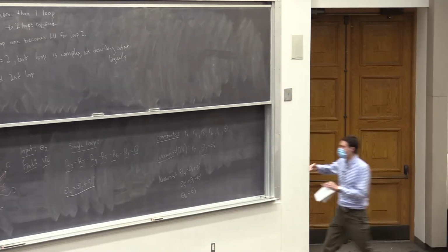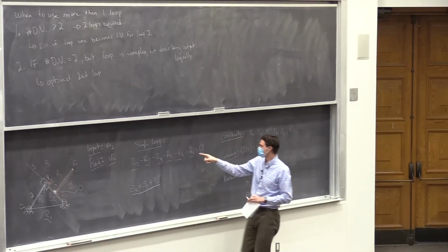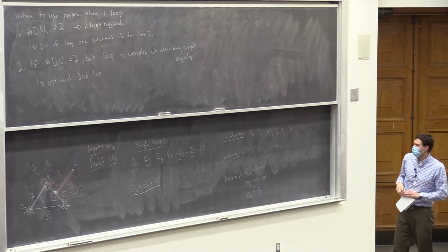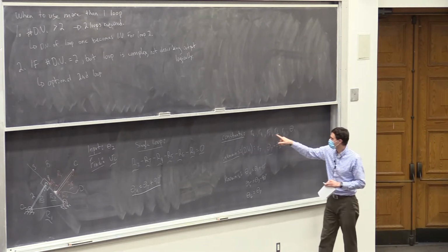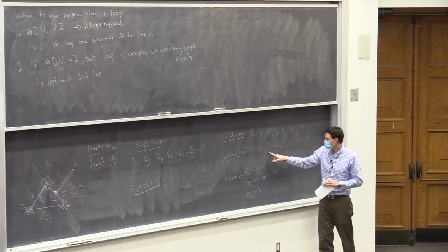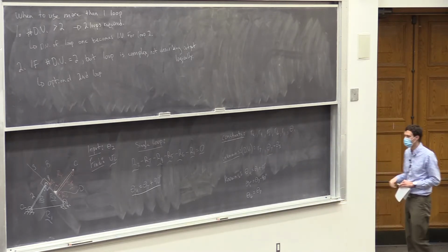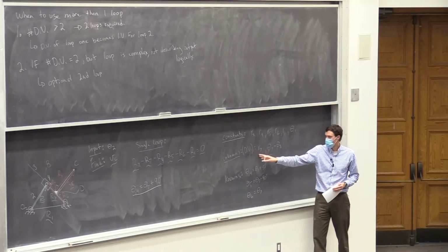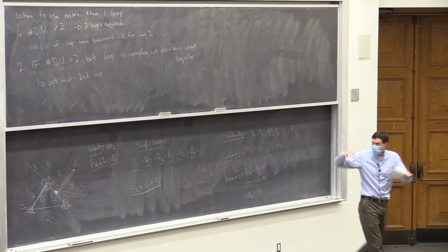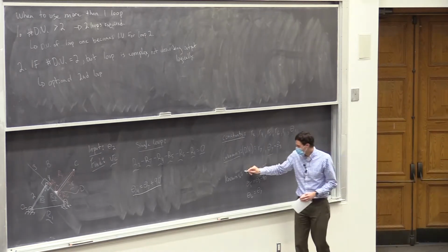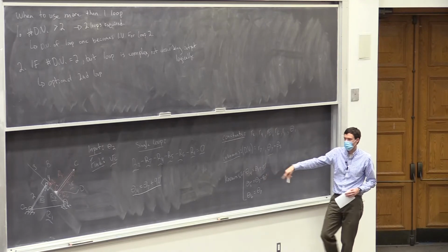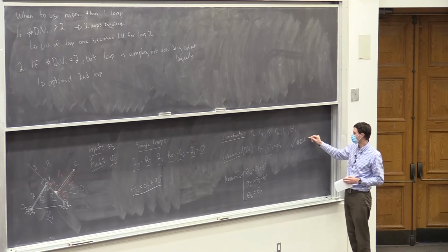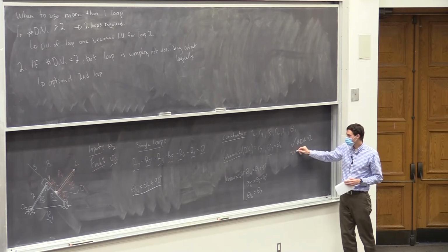Whew, so there's a lot, right? We have how many vectors? 1, 2, 3, 4, 5, 6. There should be 12 parameters, 12 variables. We have our input, 2, 3, 4, 5, 6, 7, 8, 9, 10, 11, 12. Okay, we kept track of everything. And how many unknowns do we have? Just 2, theta 7 and R7. So this one loop is big, it's complicated, but because of these knowns, these relationships between some of our vectors, it turns out we only have 2 dependent variables. So a single loop can solve this problem.